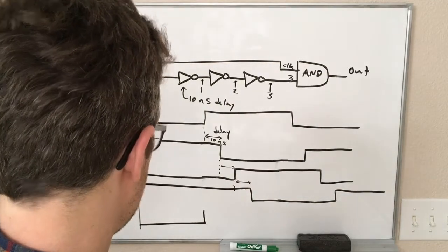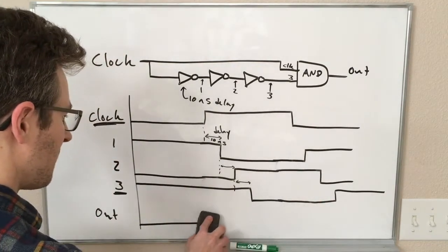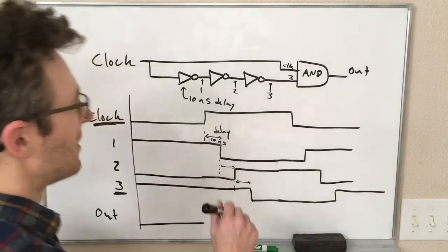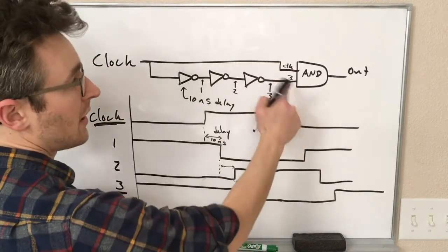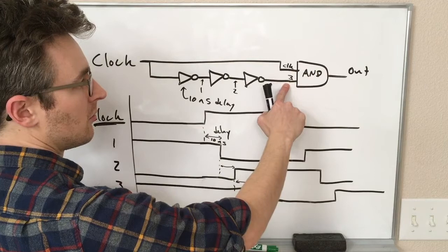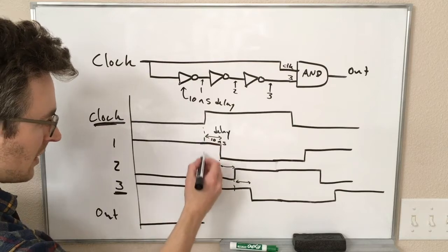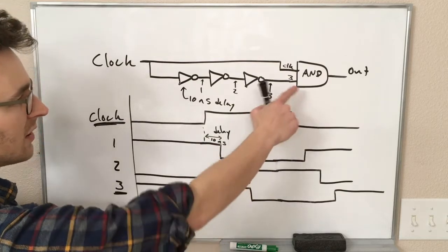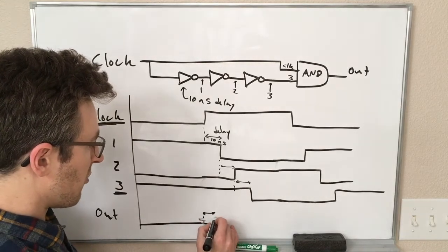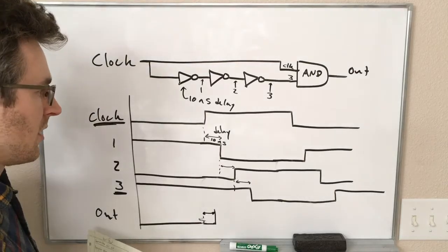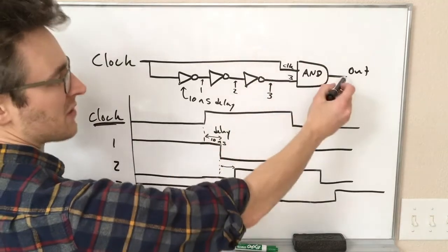Sorry, wait. Oh, right. Okay, so I thought there was an error, but the error is up here. So there's another delay also, because when the clock and 3 both give this the on input, that would happen right here, except there also is a delay from the AND gate. So there's another 10 nanosecond delay that happens here before this turns on. So really, it turns on when the clock turns on, except we have to add this delay for the AND gate.